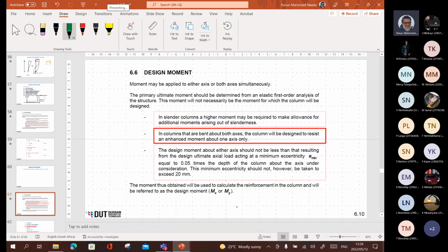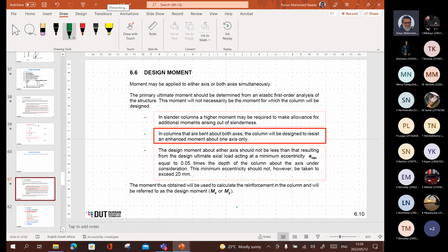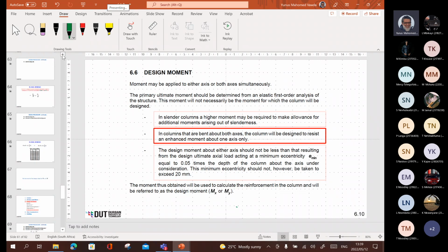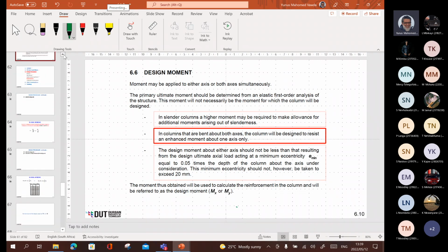Concrete's using deemed to satisfy conditions. You don't actually deal with the stress in each direction, just like deflection. Deflection was a deemed to satisfy. Use table 10, table 11, and a T factor, and if it works, you don't do the detailed calculation. Right, so similar thing with this.